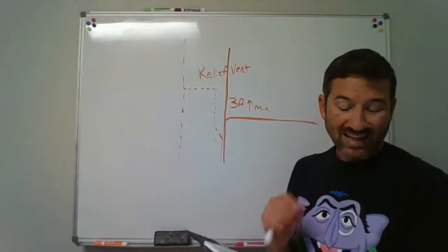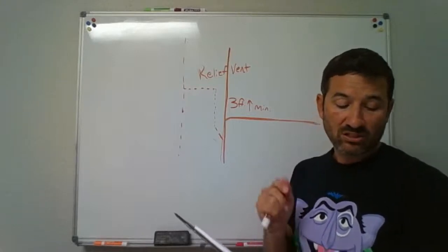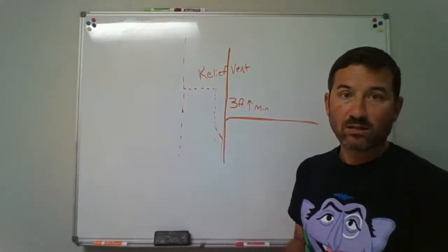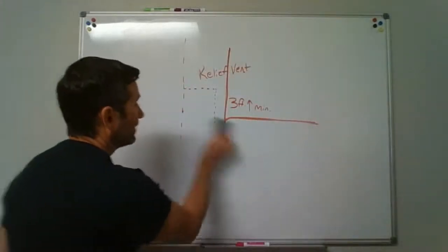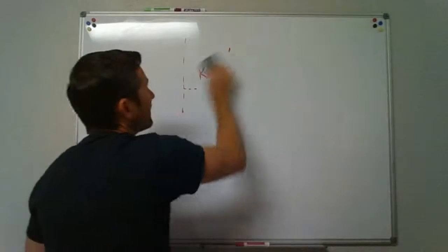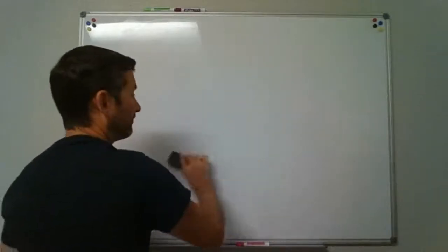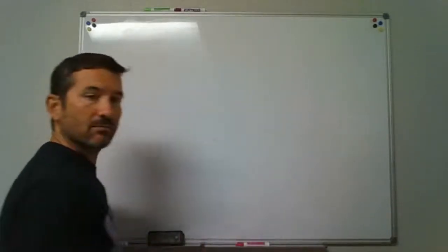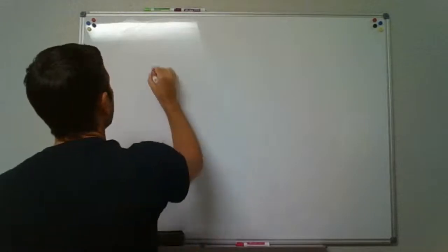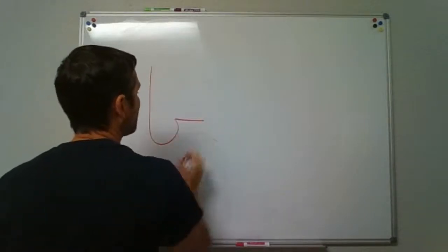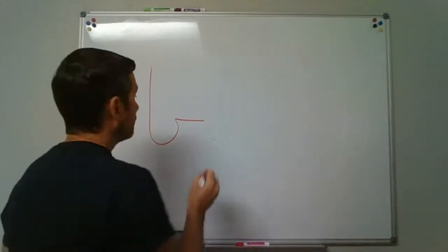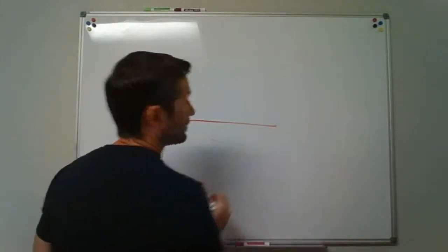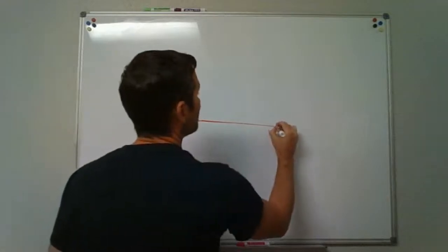Okay, table 909.1, maximum distance of fixture trap from the vent. So now we're getting into that bit of information that I normally talk about. One of the first days of getting stuff down in your notes, when we talk about every fixture having to be trapped, we talk about P-traps and all the parts and everything about those. We said it, and then we talk about every trap has to be protected by a vent.